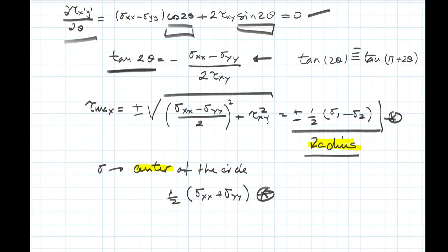However, as we have determined many of those quantities, it is not redundant to draw the Mohr circle, but it is important also to find what are the angles where those principal stresses are found, because we have derived until now the values of the principal stresses and principal shear stress, but we don't know at which angle they are acting.